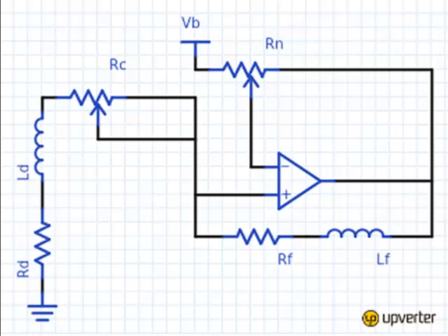Doing the math, you see that if we attach a very small inductor to the electrical side, and if that's the only thing, it will keep the capacitor stable, because when you transform an inductor across a gyrator, it becomes a capacitor. So what we wanted here is we wanted to use negative impedances to eliminate the resistance of the coil and lower the inductance to a very low number, and that's what we attempted to do here.